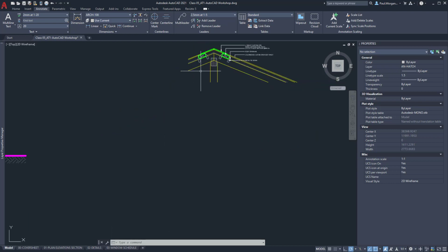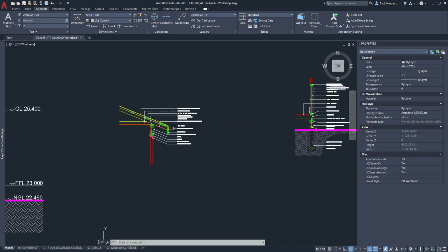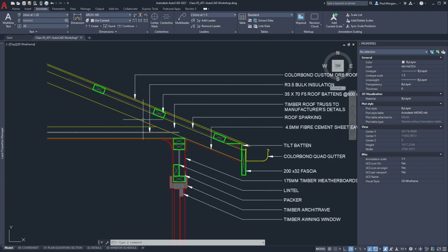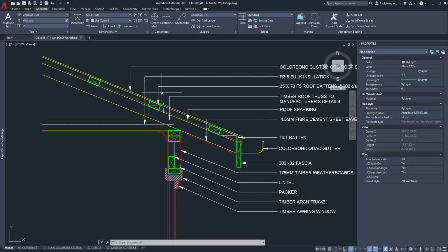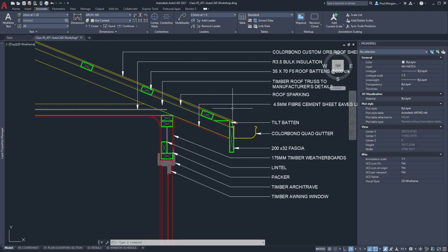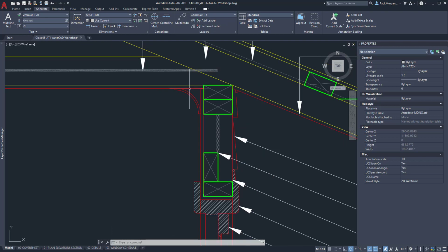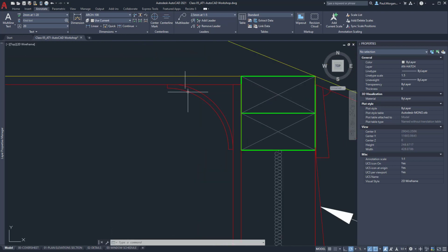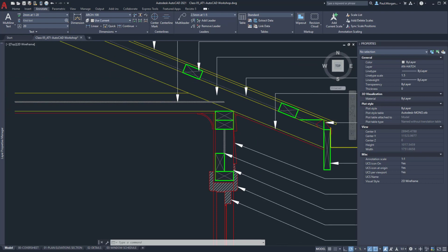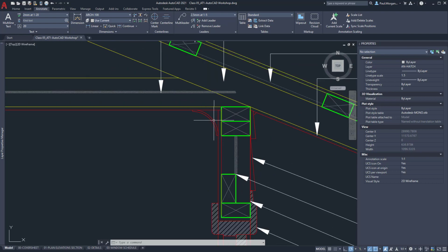waterproof membrane. Going to some of the other details, there's not much extra to really add in here that you haven't already done in the subfloor detail. The only other item of note is the cornices for your junction between the ceiling and the roof plaster, the wall and the ceiling plasterboard, which is simply just a creation of two arcs or two circles that have been trimmed off and then offset to give the thickness of that element.